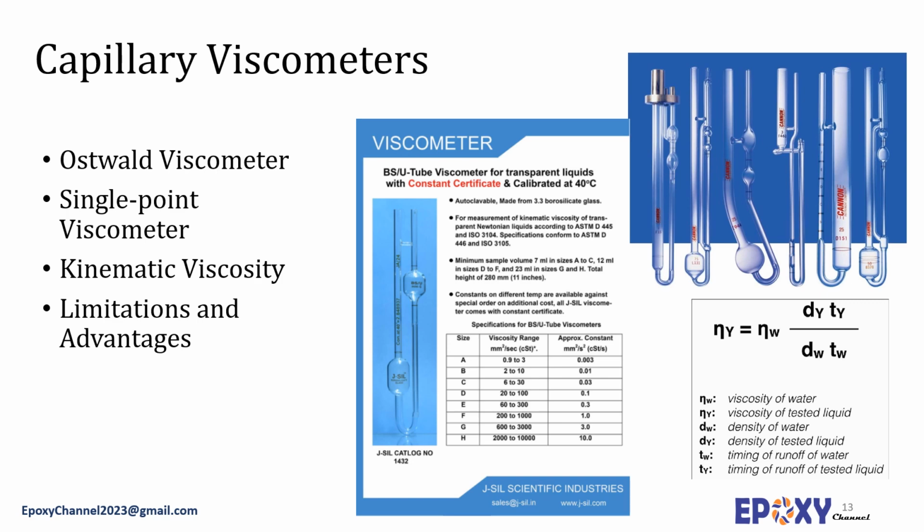Both are U-shaped instruments, have two glass bulbs, and use capillary tubes. The key difference between Ostwald and Ubbelohde viscometers is that the Ostwald viscometer is suitable for measuring low to moderate viscosity liquids, whereas the Ubbelohde viscometer is suitable for measuring high viscosity liquids. One major advantage of the Ubbelohde viscometer is that the values it obtains are independent of the total volume of the liquid used.